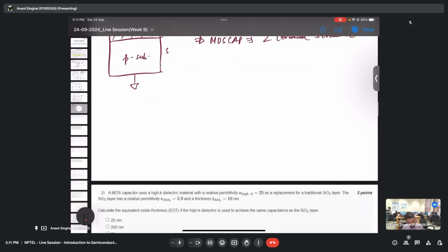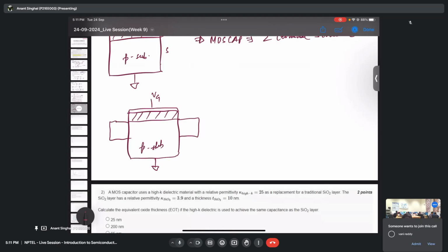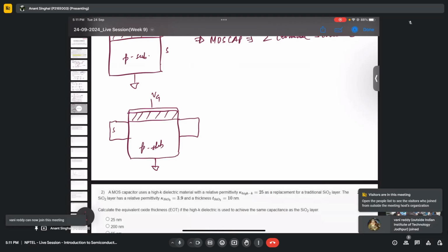So for a MOSFET, what do we have? We have the same MOS cap, which is the heart of a MOSFET. So we still have this oxide, we have the metal, we have this Vg, we have the same substrate, and we have the same ground, the body. What we additionally have, around or below the oxide layer, is two additional implants, or by diffusion, an additional source and a drain.